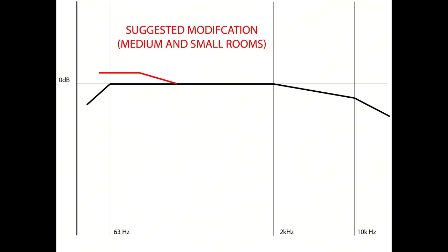But anyway, in a room about that size, a medium or small commercial cinema, and in particular in small home theaters, that gently rising mid bass and elevated low frequency tends to provide the most accurate timbre in my experience. In fact, if you take a well-engineered speaker that measures flat anechoically, say something from Harman or Revel, where they follow that principle pretty closely, you're going to see some elevation in the bass area relative to the mid-range.